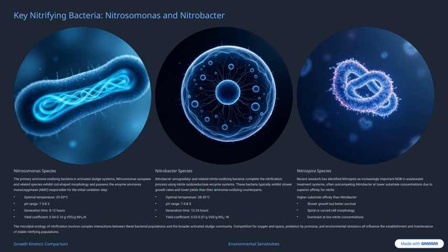Finally, regarding environmental sensitivities, nitrifying bacteria are quite sensitive to changes. They are more vulnerable to temperature fluctuations, pH shifts, and toxic compounds than heterotrophic bacteria. This means that careful process control is essential, especially to avoid shock loads that could upset this delicate microbial balance and compromise the nitrification process.